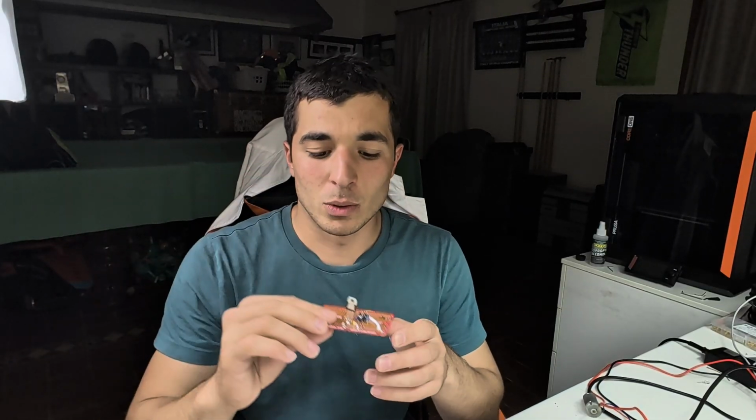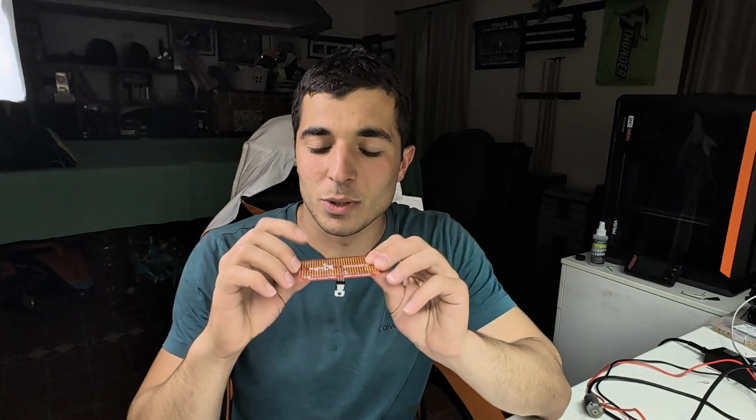Now, the 3 problems that we covered were, again, how to not blow gate drives and how to calculate peak current so you don't blow MOSFETs and all that sort of stuff. But the third one I didn't really mention: these boards have a 6-pin adapter, and I just slotted it into the perf board, thinking it was pretty tight, so all pins were contacted.